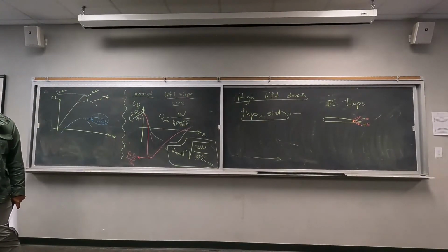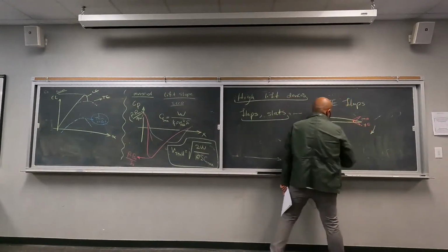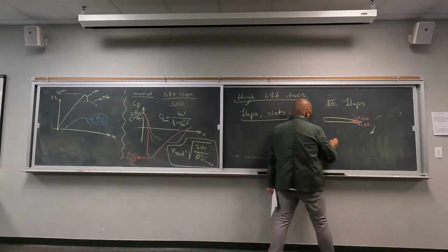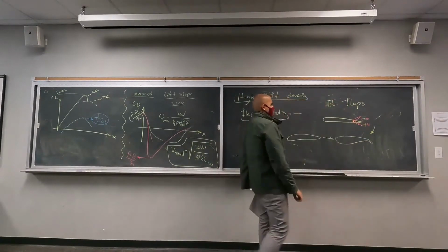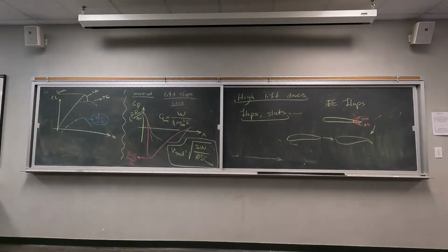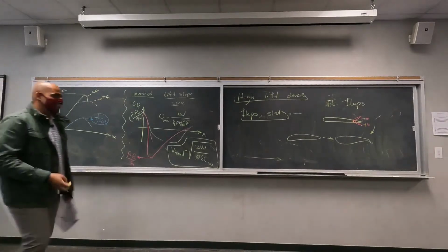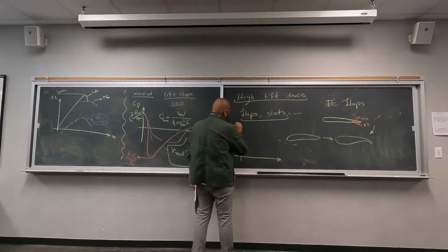What will happen to your lift, CL versus alpha, when you change the angle in this direction? Again, your airfoil is like this, then it will look like this, right? With a positive trailing edge flap angle. We had two main mechanisms, right? What is one mechanism we are working with here? Which one have we chosen to work with here? What are we changing? The camber, okay? So what do you expect should happen to CL versus alpha?